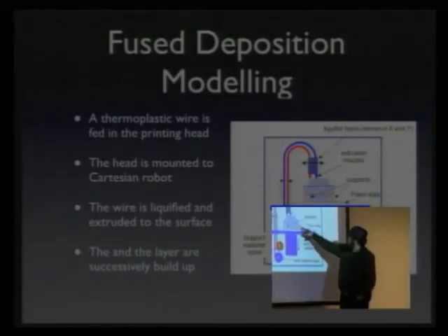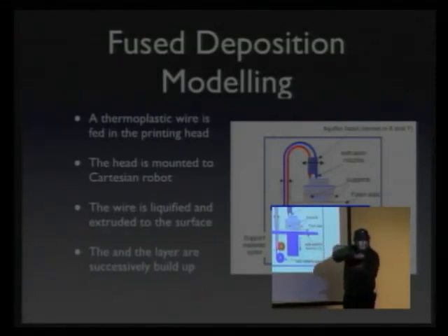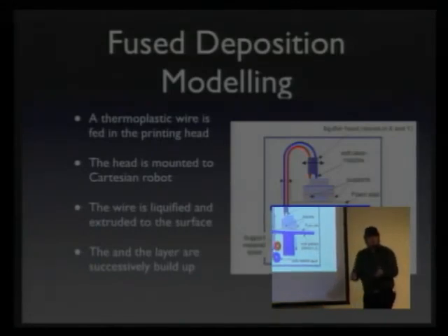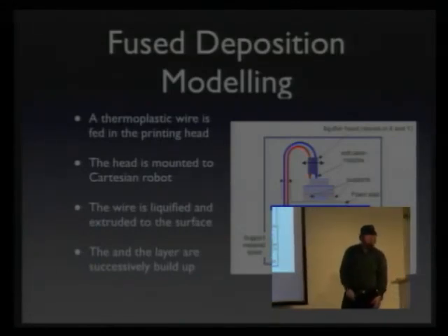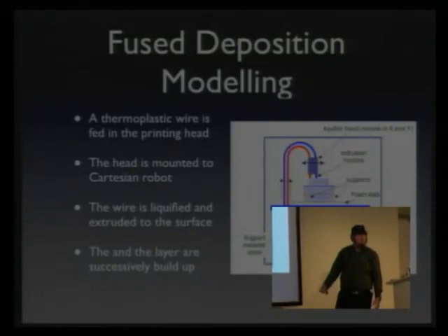So you use the 200 degrees one to make support structures and really extrude them out in lines so that you get your structure this way. And then you can extrude the other one on top, put it back in the oven at about 300 degrees, so the support material will melt away, the other one will still stay.